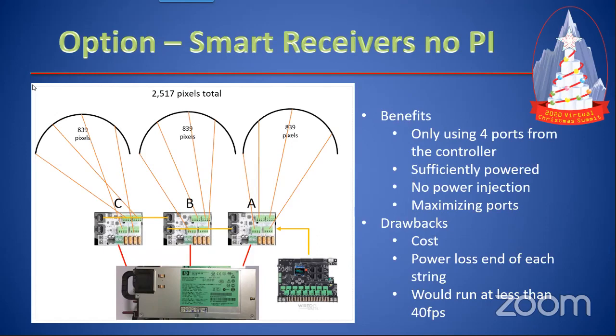So our smart receiver is also 30 amps, though of course by the 4x5 amp fuses. Yes, they actually are 30 amps. Can you run 3 receivers off of 1 power supply if you daisy chain them? Yes. Good practice is a fuse between the PSU and each input rated for the input of the board.